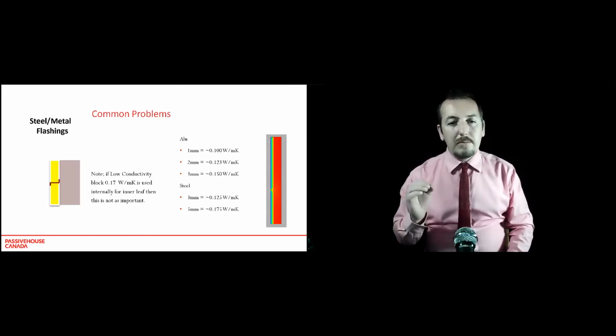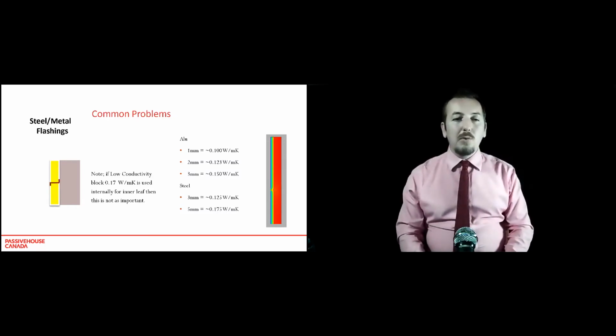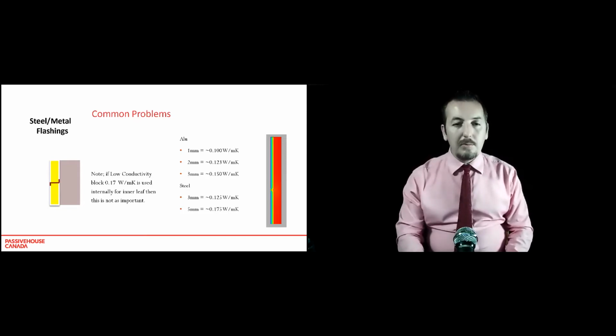And where this is most common is aluminium starter tracks. Nowadays, what we do is either use a PVC starter track, or we just use a drip edge on the outside and a starter piece on the inside, and then use a rubberoid flashing over it. But it is something to watch for, and can cause massive heat loss in buildings, in passive house, and can be overlooked too.